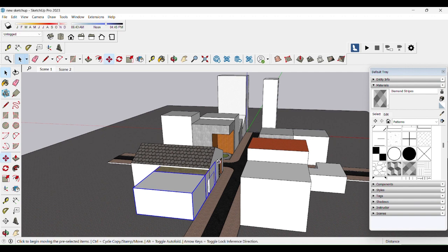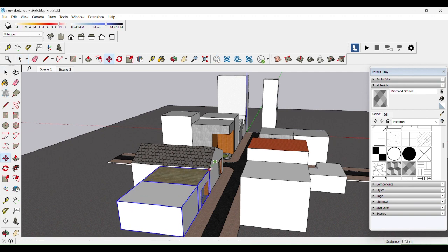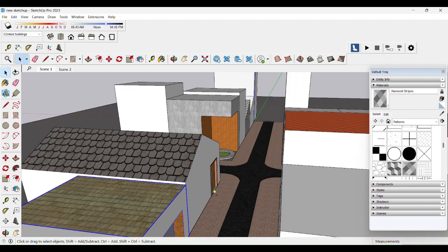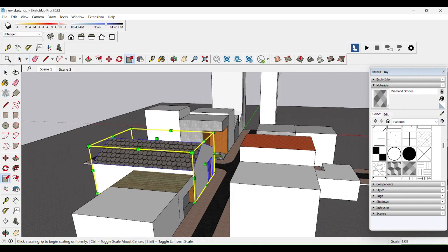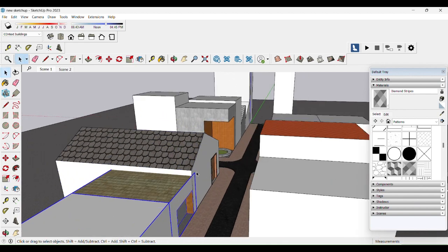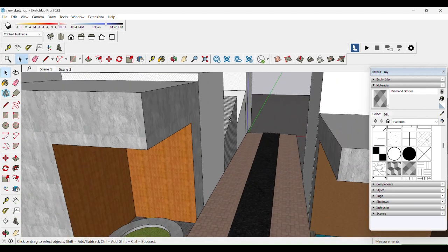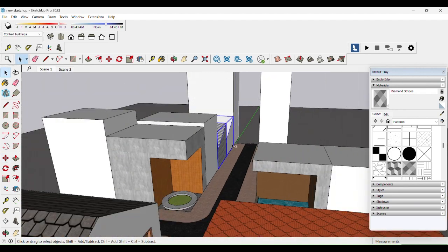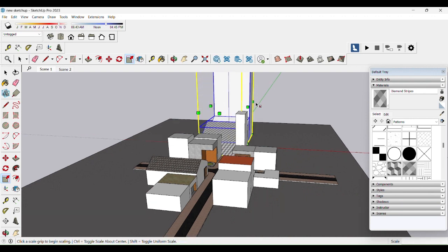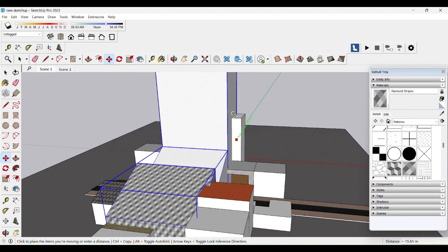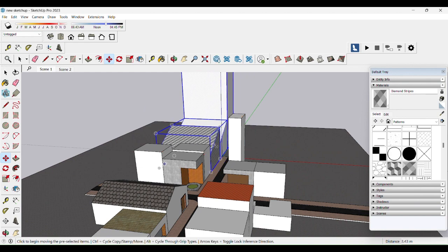And then once you open back the Lumion with the SketchUp file on, you just see this. Let's increase the whole context size. Scale it. Again, move this back. Now it's almost the same. Let's check the height. Checking and measuring the height is the command T. The tape command opens. So let's increase it more.